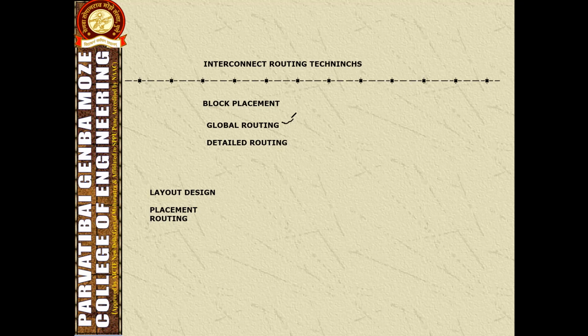The rules used in routing are: the first net to route should have critical delay, then route the wire early to get them out of the way. Don't be afraid to try to rip up and reroute wires.